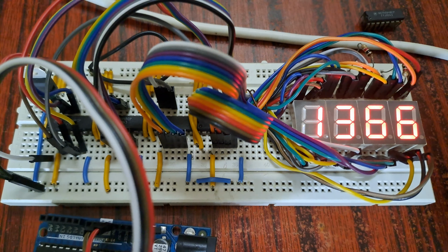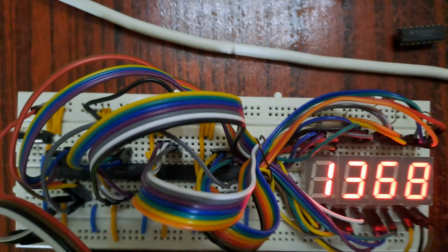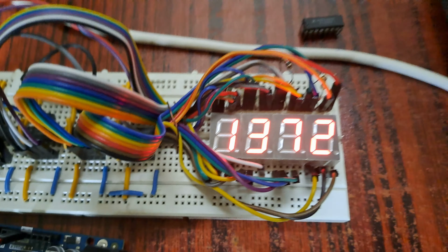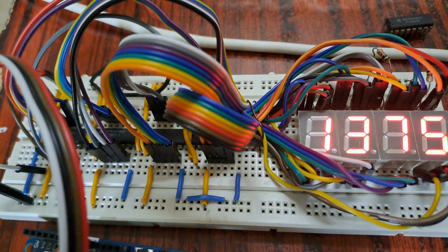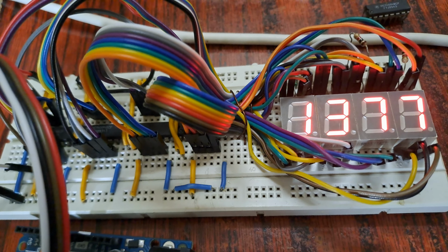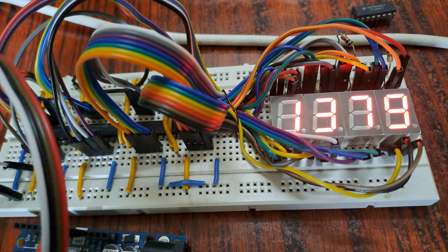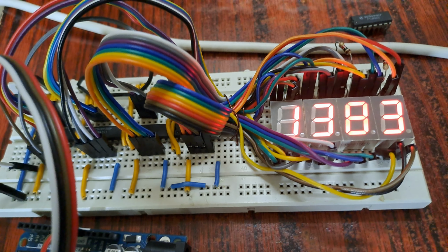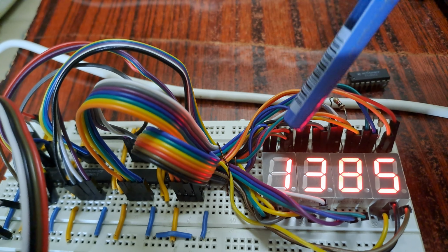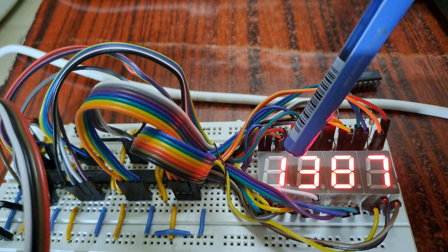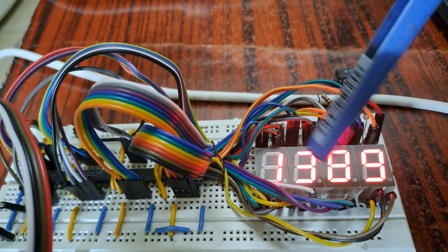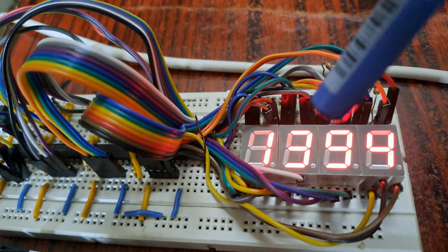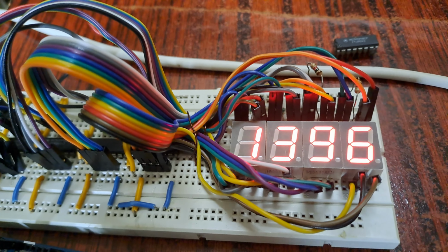So they are being fed from the Arduino Uno board into the breadboard, and it is fed to the shift registers. You can see the shift registers, the ICs, down here. So the clock and data is being fed. Now this is a serial in parallel out application. Serial data is fed in and parallelly we are getting the data, and the data is being fed to the display. So basically I am transmitting this 1388 serially from the Arduino Uno, and it is displayed in parallel mode on the 7-segment display.